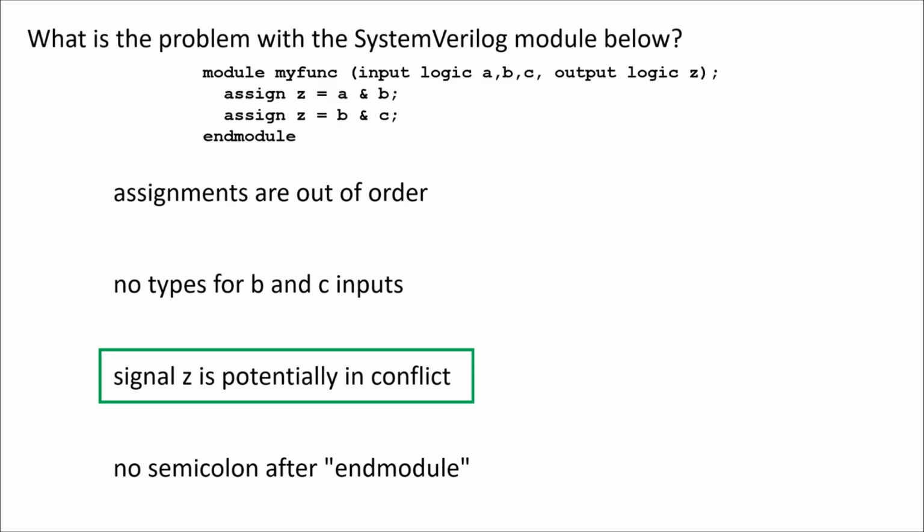Okay, interesting. So I guess that would be if you're working with a mixed push-pull design where some will naturally be a weak drive logic 1. Yeah, to pull that part down. Or if you had a different one in the same hardware that defaults to logic 0, you have to pull it up. Now that you mention it, SystemVerilog has a concept of weak 1 and strong 1 and weak 0 and strong 0.